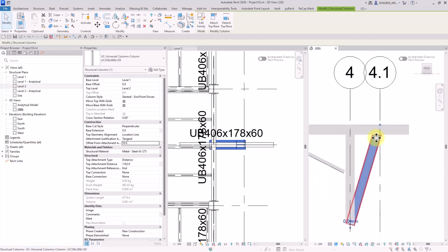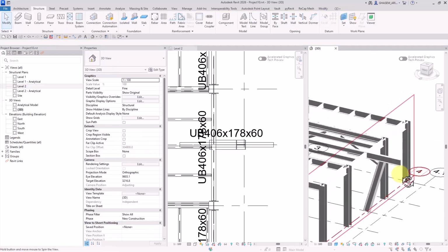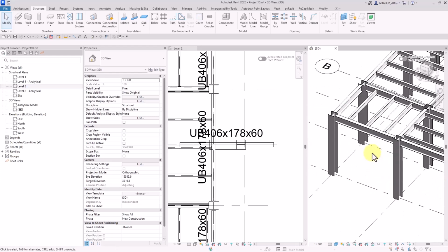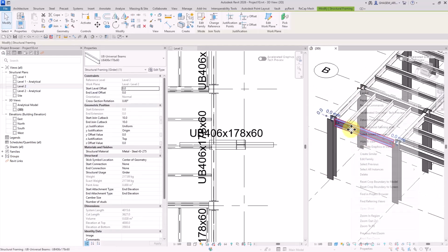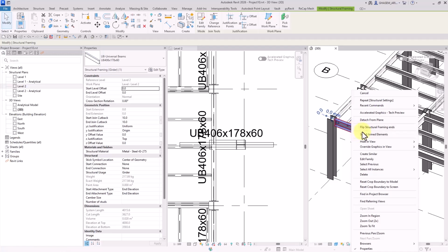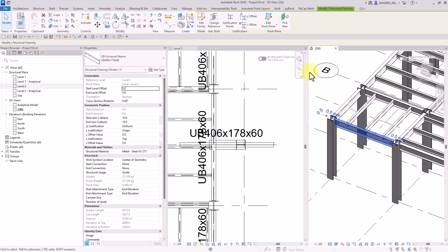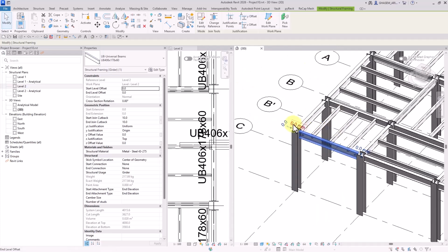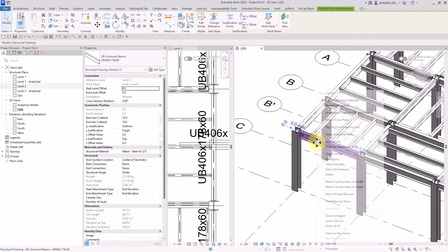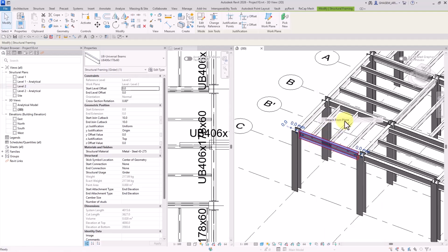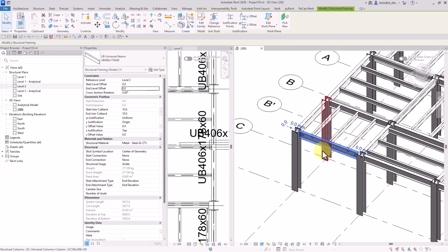Alright, now let's talk about some other features that we actually had in previous versions as well. Again, as some quick reminders. Like if you select this and do a right click here, you'd find detach from plane. So guys, basically when we set these based on a reference, it could be a reference level or reference plane, doesn't matter which, reference level and work plane would be deactivated in the properties. And we can use this item to detach it completely. And after that, we can modify these items and parameters.